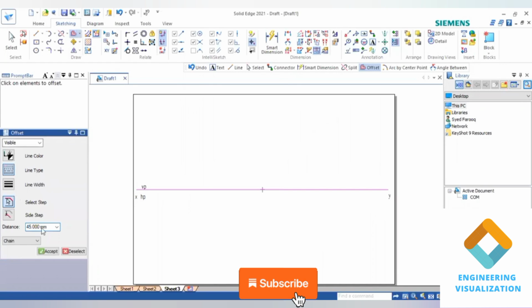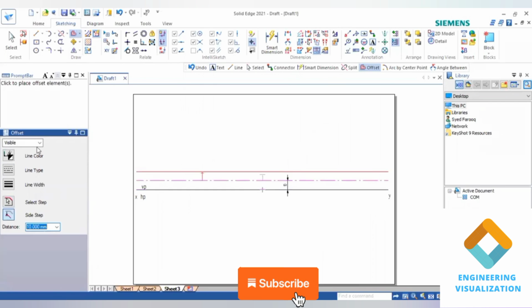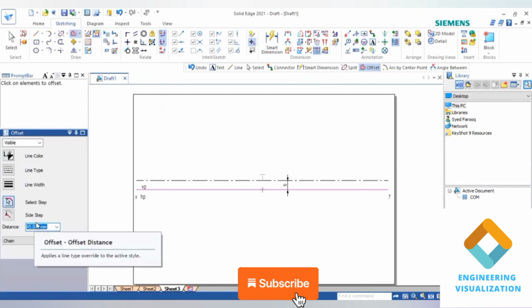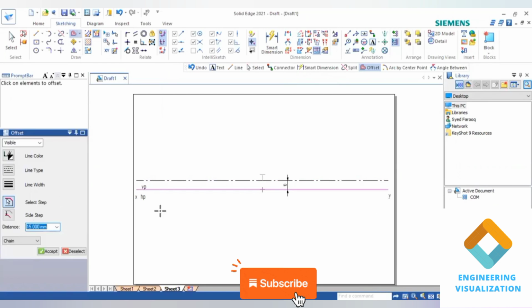Now we have to draw these locus lines. I'll be using offset command. So select the XY line and give the dimension 10 mm. In the same way again you select XY, give the dimension here 15 mm. Okay,